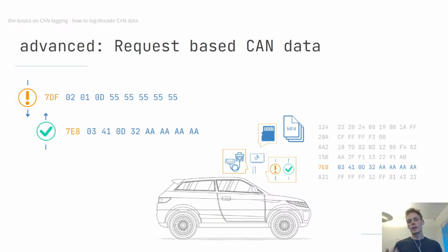So you do this on a regular basis, and that gives you essentially communication in the form of CAN bus frames, which you can decode because you have the OBD2 DBC file, because we provide that free of charge on our website. So in other words, for those types of use cases, all you have to do is configure your device accordingly. And obviously for our devices, and you'll see this across other devices as well, because OBD2 is such a popular protocol, we provide plug and play configuration files for that particular use case.